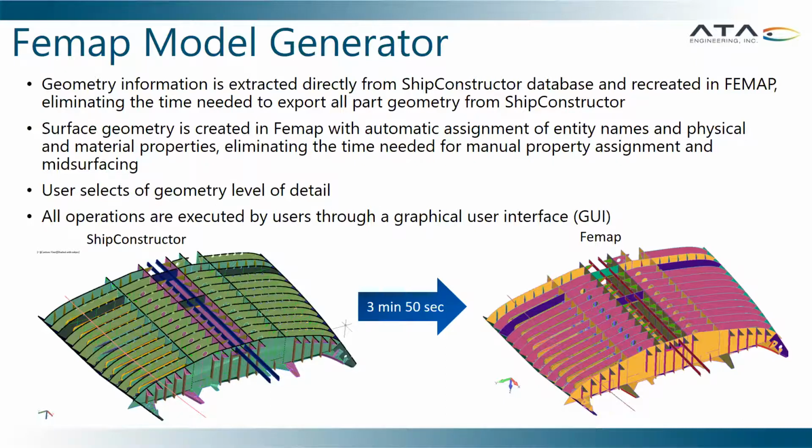Because of the size of these ship sections, even the export and import step can be quite time consuming. And then of course the mid-surfacing, if you've ever done mid-surfacing, you'll know that that can also take quite a while, because first you have to mid-surface and then you have to make sure all the parts intersect with each other and extend surfaces. And that's generally the part of geometry preparation that takes the longest.